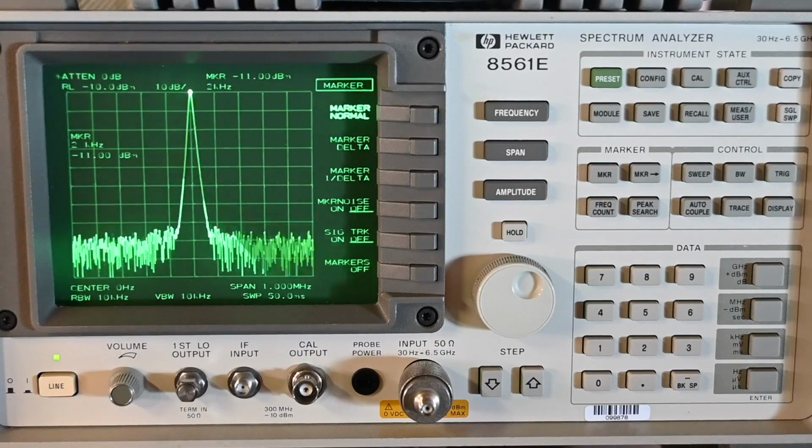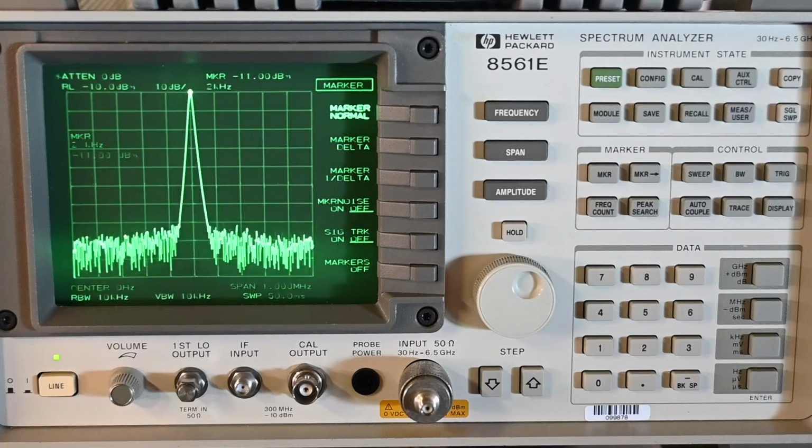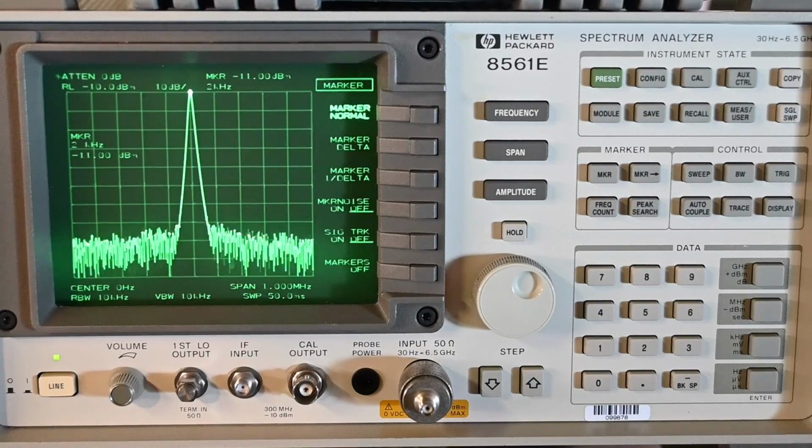It says if the local oscillator feed through amplitude is within the limits but signals are low, which is exactly what we're having, then the RF path following the A8 mixer, so assembly number 8, is probably operating properly. So that actually eliminates a lot of the internal components, so the problem is likely before the A8 mixer. So let's take a look at the block diagram and see what that actually points to.